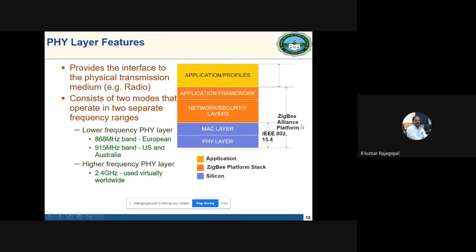It is nothing but network facilities, whether acknowledgement is available or end-to-end communication is supported, and other facilities, topology related, etc. All the other network functionalities will be added with the ZigBee platform only. So if you want to use the base 802.15.4, that is one option, technically the base standard is 15.4 only. But additionally, whether the ZigBee suite is used or not is your recommendation. If you want network facilities and all the additional facilities, then the suite will also be taken.